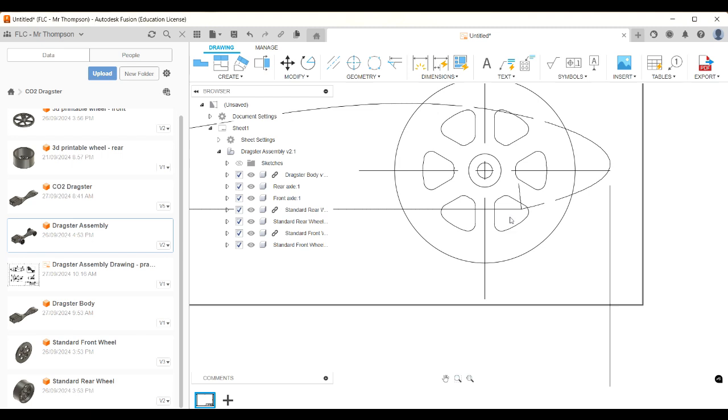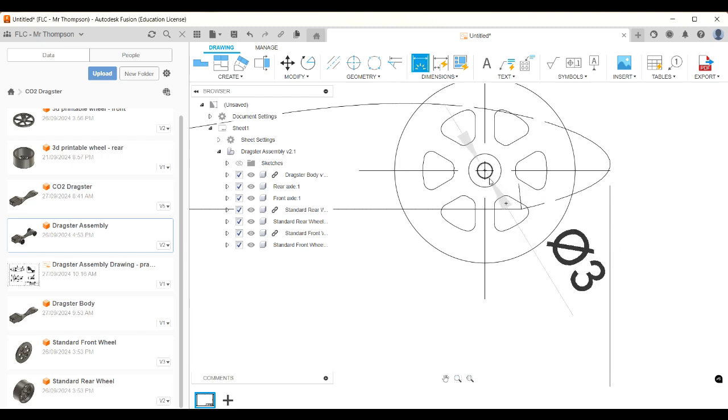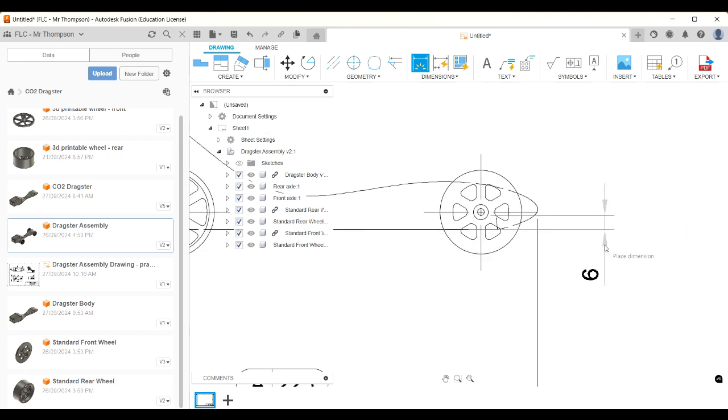So what I can do instead, D, when I'm clicking on that circle, I can right click on the circle, and if I come down and choose curve XY min max, what that means, it's going to allow me to choose the edge of the circle, either the very top or the very bottom or the very left or the very right of the circle. So if I click there, now I can choose that point there, and now I can choose that bottom line there, and you can see now it lets me, if I zoom out, that measurement there is 6. All right.